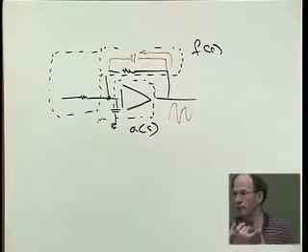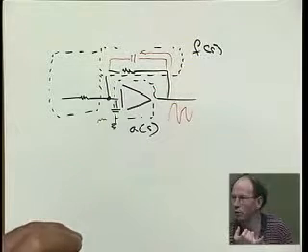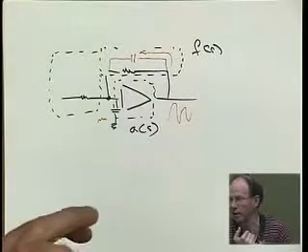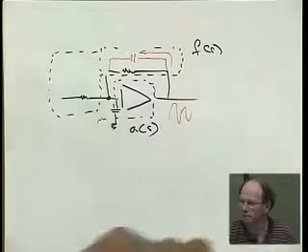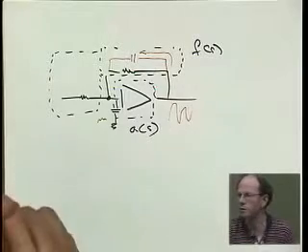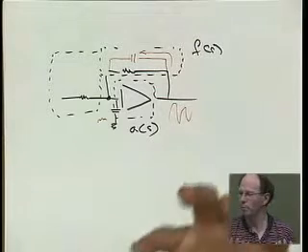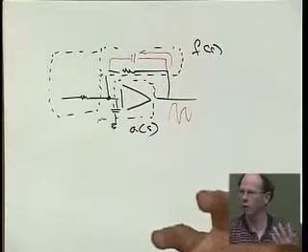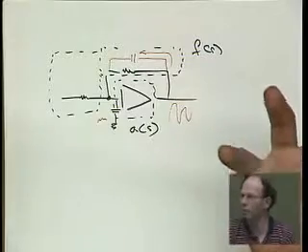There are also other strange things, like I found papers on. Not too surprising, if you make an approximation using two ports, you of course get a T of S, a loop gain that is hopefully very close to the real thing. Sometimes maybe it is the real thing, but usually we'll make a little bit of an error. Heck, it was an approximation, totally normal. If you do a return ratio analysis, you may make different assumptions, no assumptions, so you get a different T of S. Well, I've seen papers that compare these two and sort of puzzle over their difference and say that the return ratio and the loop gain are two different things. Well, that's a very bizarre thing to say.